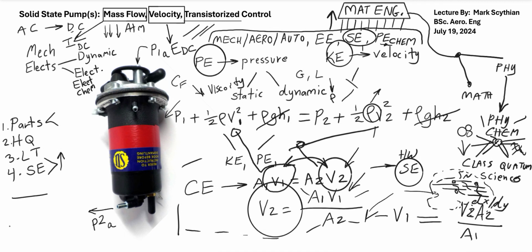So in wind tunnels, that whole dynamic viscosity controller is artificially controlled by having a degree of freedom on the temperature. So wind tunnels can do things like artificially heat and cool the airflow to some extreme temperatures so that Reynolds number scaling is accomplished. So you have to also take the Re number into consideration, and the 3000 point is the transient, greater than is the turbulent, and less than is the laminar.